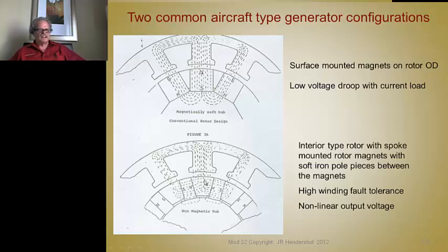That's carefully designed so that the voltage drop from the flux linkage drops as a function of a certain current that allows the short circuit current to be sustainable. And so this is really a field weakening that takes place. It's a highly fault tolerant machine. This was developed by GE, by a research group up in Schenectady. To this day, aircraft generators are made this way.